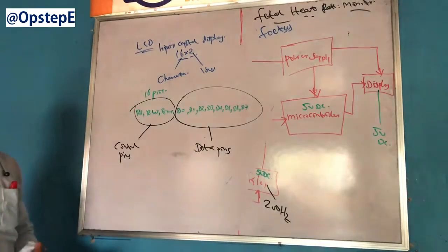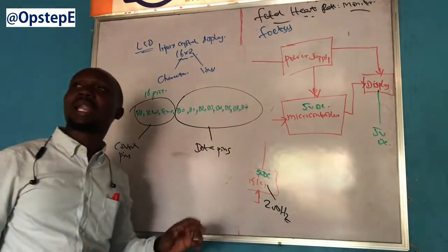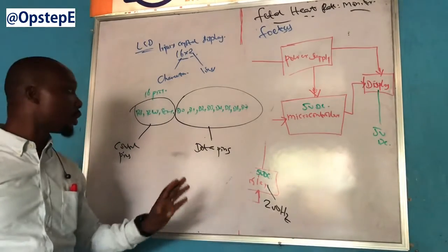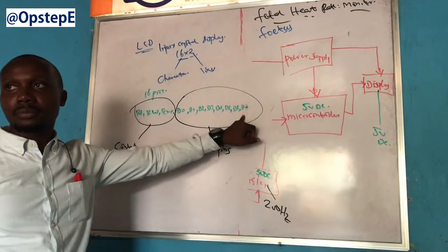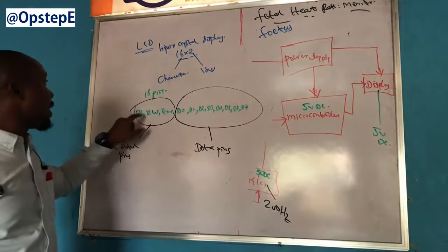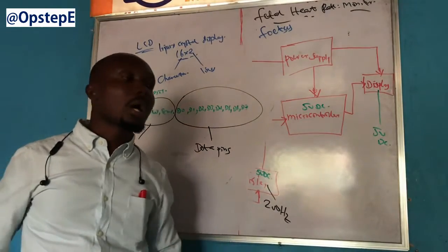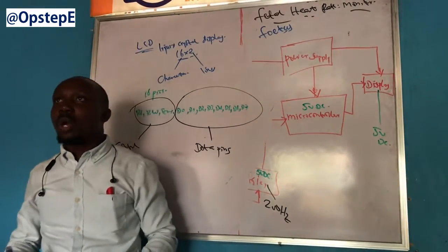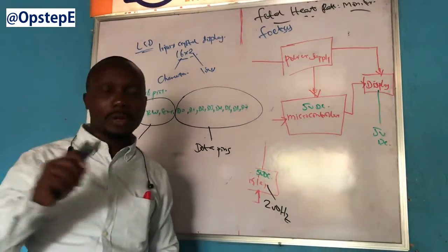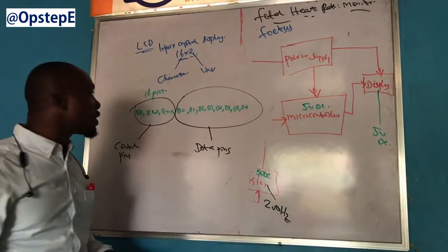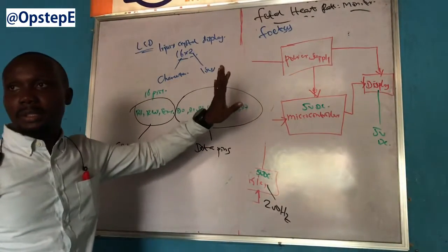What it means is that this is where information, characters that you plan to have displayed on the screen, are sent to, between D0 and D7. Your RS and RW are where you set controls, set how it is displayed, when it is displayed, and other things it does. For instance, you don't just send characters to the display line.